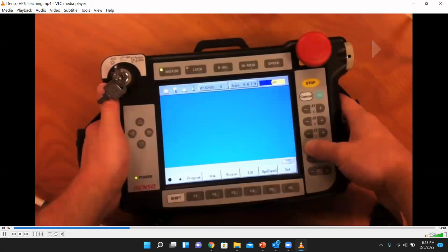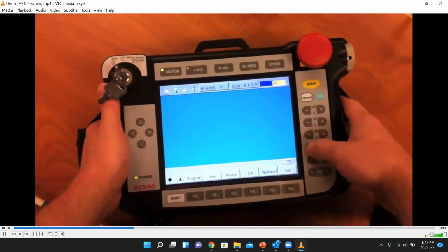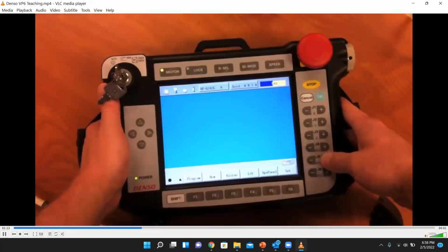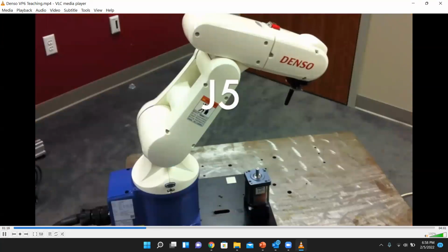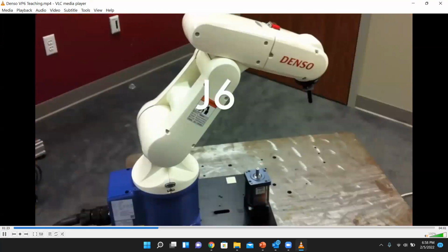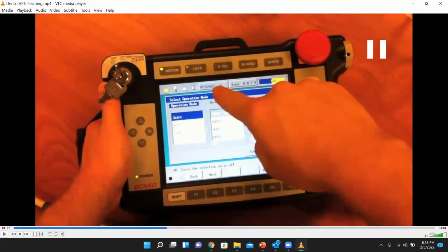So J4, that is fourth axis, that is fifth axis, J5, and that is the last, and lastly J6, which is the rotary motor on the end effector. It's rotary motion. Right? So the last axis, sixth one, is where the symmetric tool application comes from. If you do not need that rotation, you don't need that degree of freedom.